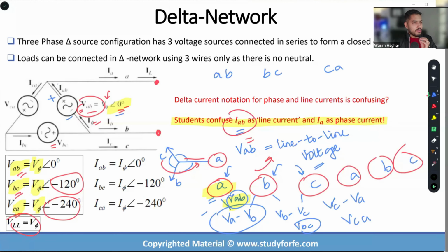So this is the level of detail and the nuances that you have to appreciate in order to fully understand these configurations. The voltages are fairly easy to understand. Depending on the phase sequence, they just have to be rotated by 120 degrees. And let's say if instead of VAB, I had VBA, then that indicates a negative sequence, and an entire discussion on the negative sequence, the ACB configuration, we can spend half an hour just on that.